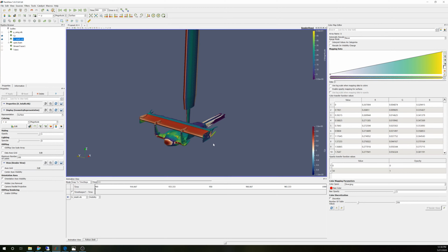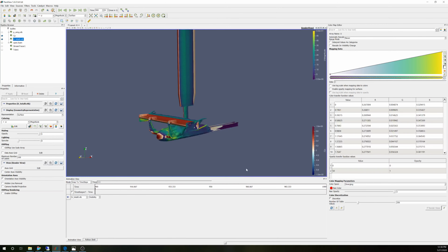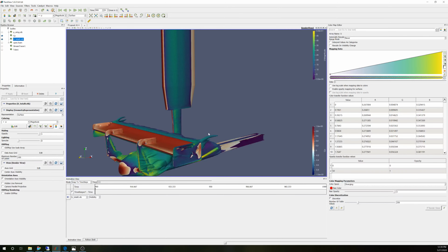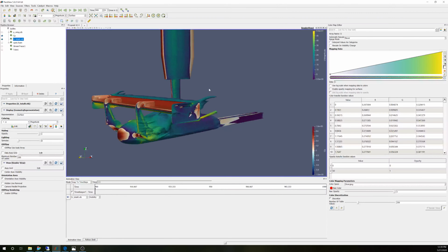You can see vortices coming off of it, and one way you can see that's obvious is you can see it coming off the end plates. So on our wing, the V1X, we have slots on the top of the end plate. We also have some things on the inside of the end plate on the bottom. It's really common to see this type of thing in Formula One.